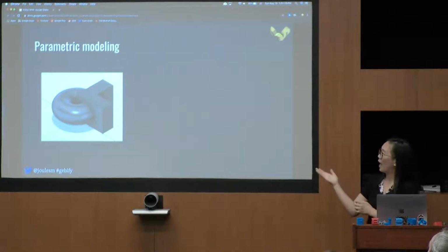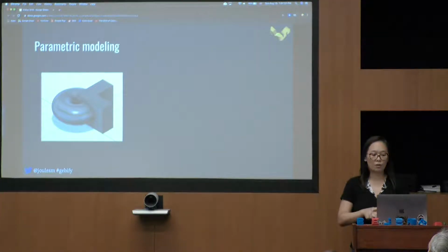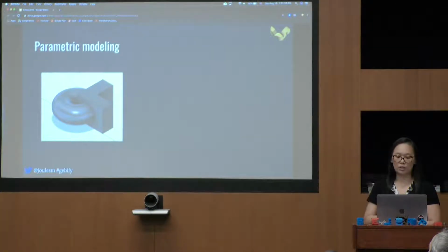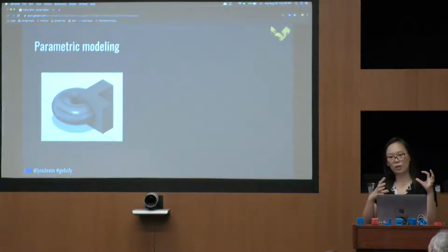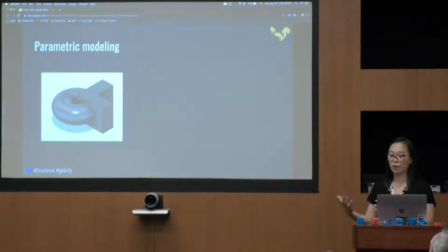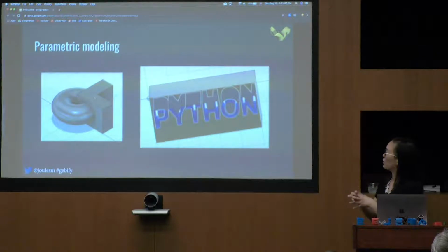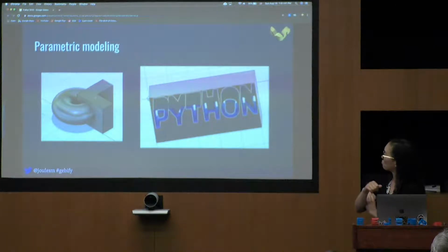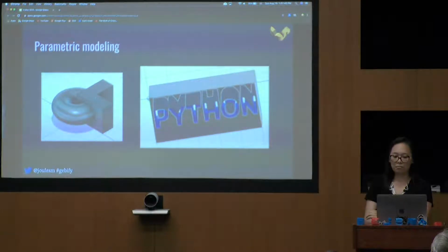As we saw earlier, we can add shapes together to get a new volume, to get something more complex. Union is not the only Boolean operation that can be done. You can also do intersections and subtractions. Like in my letter blocks, I use subtractions to create holes in letters like the letter B and the letter O. And you can do intersections to do things in 3 dimensions. So here we're doing a subtraction of the word Python in a 3D rectangle.